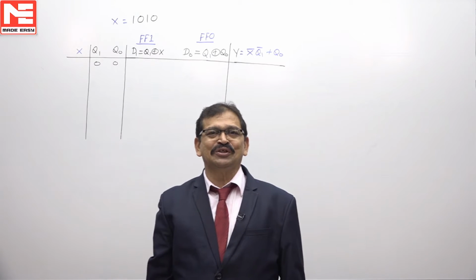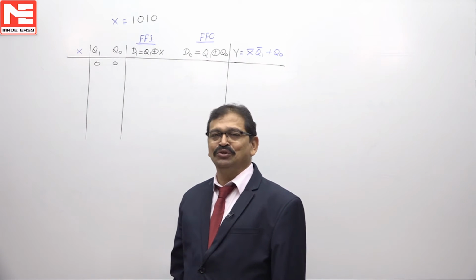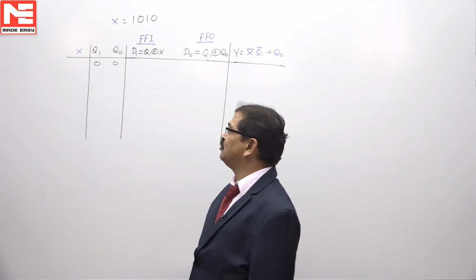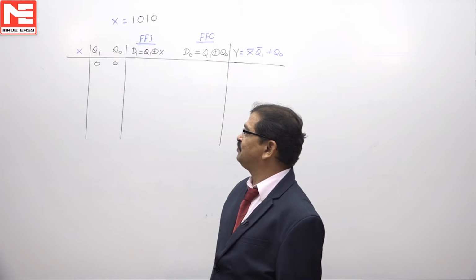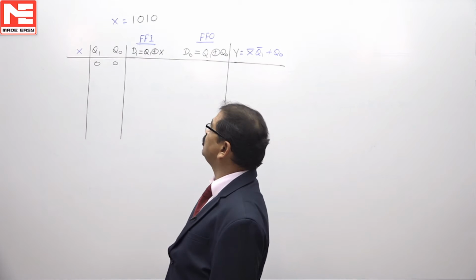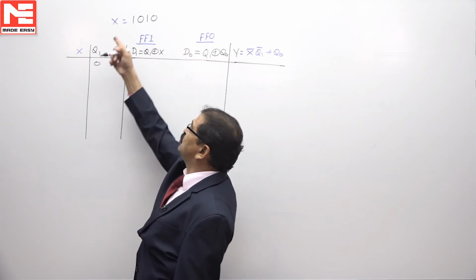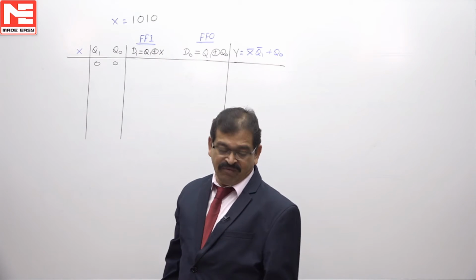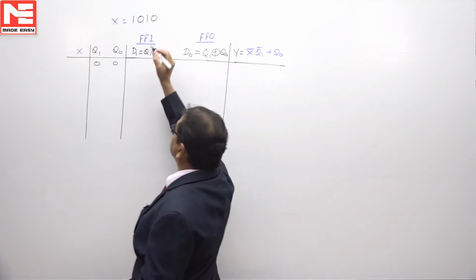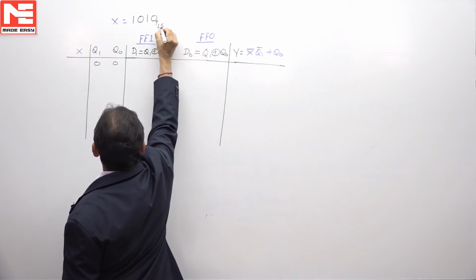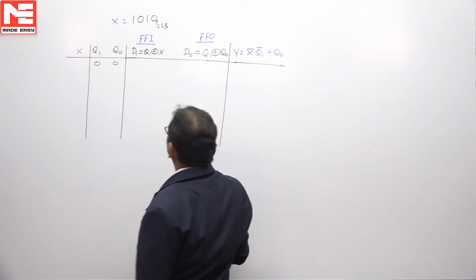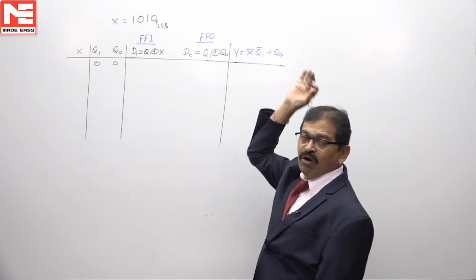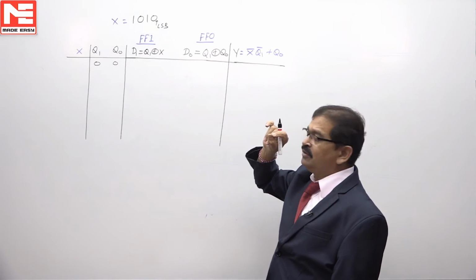So, we are looking at a sequential circuit which is built by using two D flip flops. The initial content of the D flip flops is mentioned in the problem statement as 0 0. An input sequence 0 1 0 1 will be applied, and first the LSB bit will be entering into the circuit based on the description. So this is our LSB, it is the bit which is to be entered first. For this input bit sequence, the question is: what is the output bit sequence from the circuit?